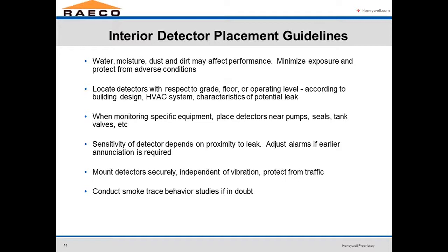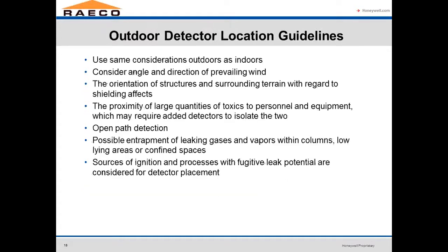Keep them away from vibration, and we've also seen that some detectors, you need to protect them from forklifts and lift trucks. You don't want people running into these things as well. It's always a good idea, if you're not sure what to do and you're not sure of what your dynamics are like, to conduct some smoke tests by just releasing smoke and seeing exactly where all your wind currents are and how your ventilation is moving.